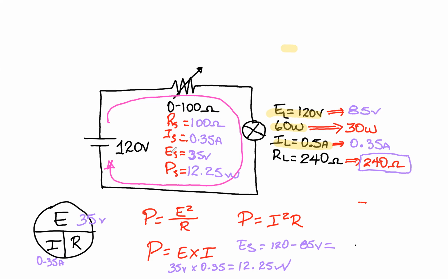So now, having this circuit in mind, I'm going to show you how we can substitute in the circuit this variable resistor by an SCR, and instead of losing all this power, we pretty much can control the voltage here without losing any power. So in order to do that, we are going to draw a circuit, but now I'm going to use AC, okay?